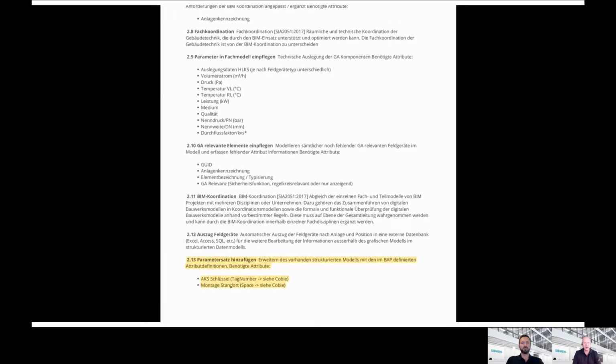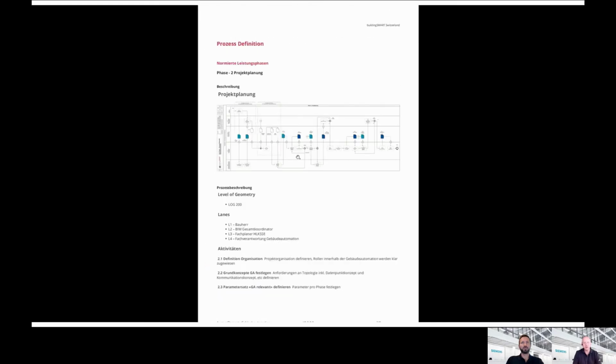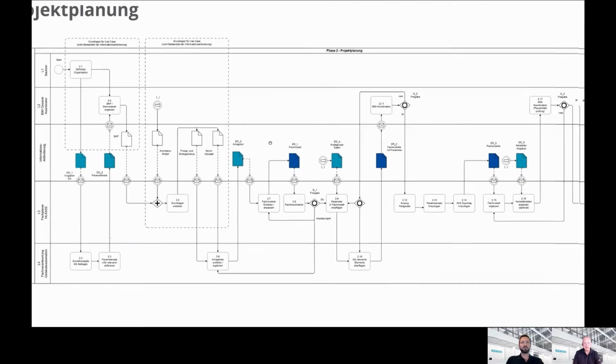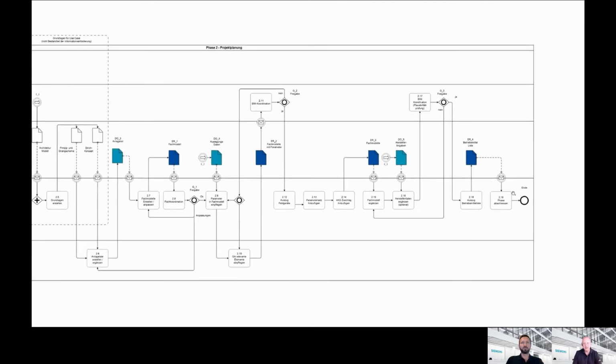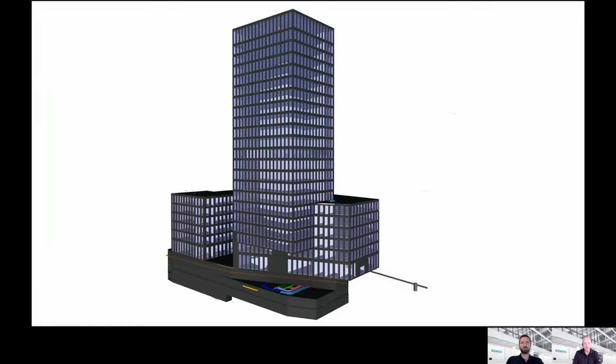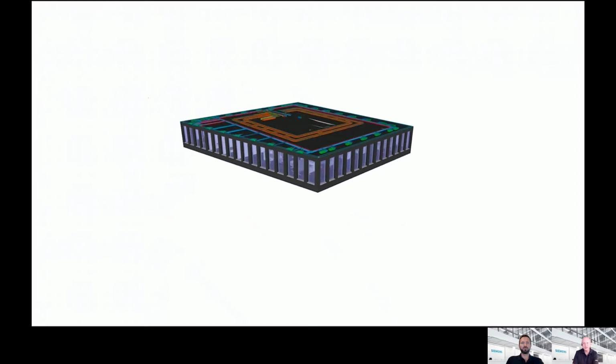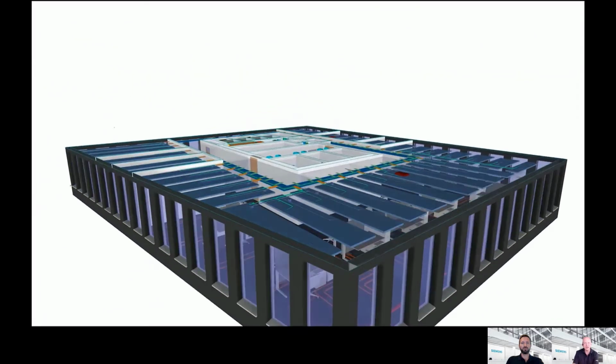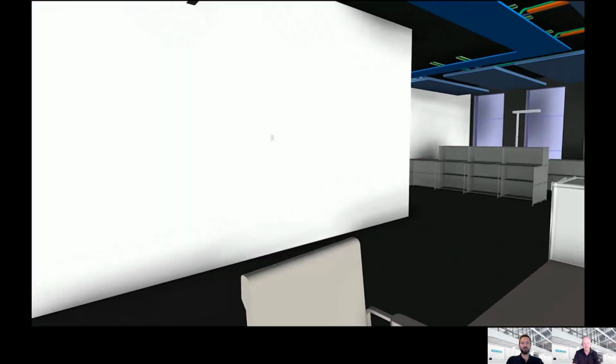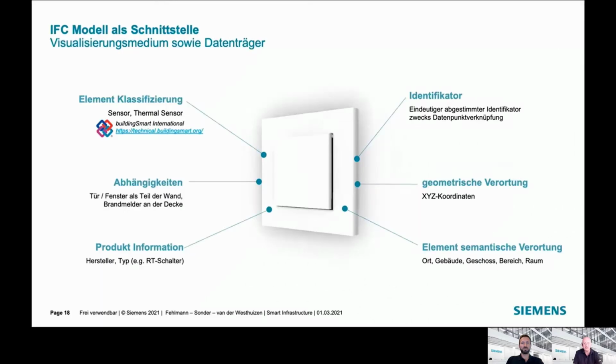We use this identifier for collaborations with the planner and electricians and as a common denominator for handover to facility management. The standardization of system ID keys with the IFC structure is a key part of this process. Information is incorporated about energy calculation, simulation, and visualizations, and for use in visualization evaluations. Windows or various other elements can therefore be used to display energy performance in the building envelope. The room elements thus become the medium for identifying all room-related statuses.